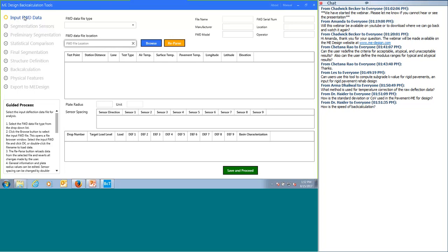We would hope and encourage future users of the pavement ME rehabilitation design, both for flexible as well as rigid pavements, that the load transfer of those transverse cracks be measured on flexible pavements, as well as the joints for rigid pavements, because it has a big impact on the amount of cracking that occurs over time from a reflection cracking standpoint.